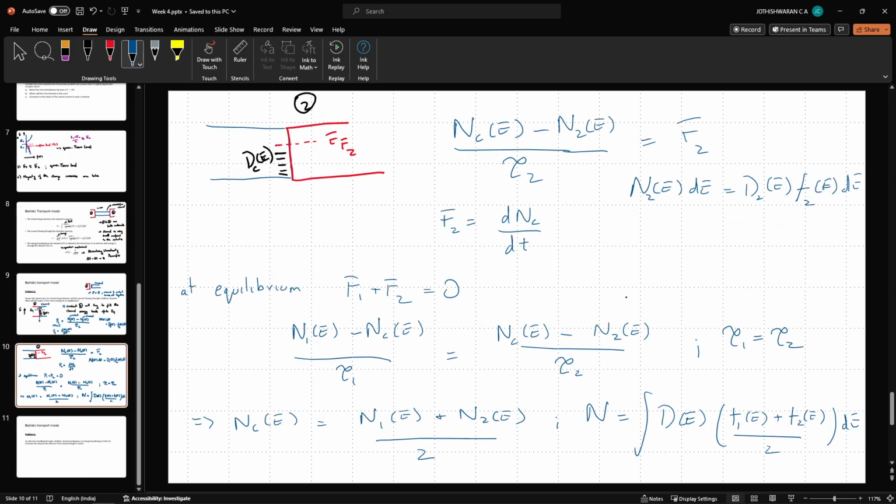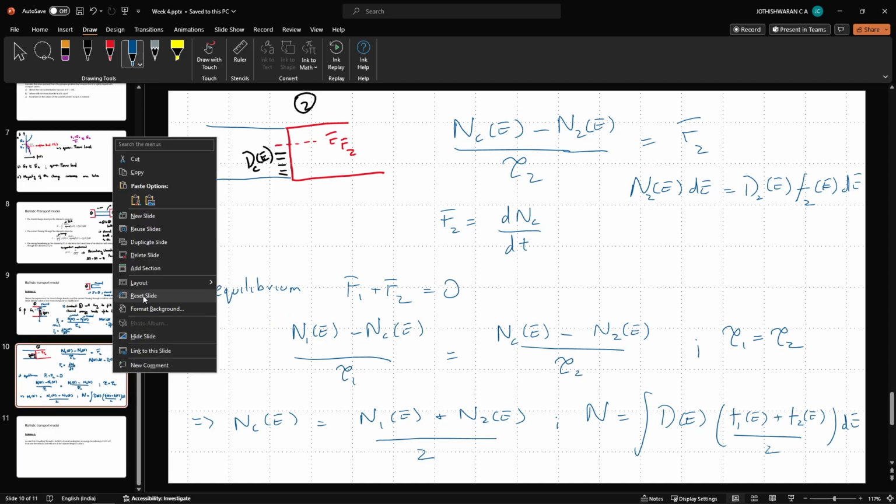Now from this we can also intuitively understand something. What will usually happen at equilibrium in the channel, up to what energy level will the electrons be present? That should give us the Fermi level across the device, or more importantly the Fermi level in the channel. For very high energy levels, they will get readily absorbed. But typically, when this average condition holds, the charge present in the device will go up to, let me just create a new slide.